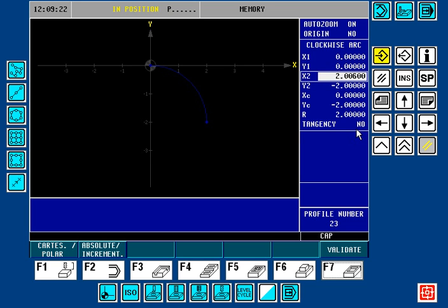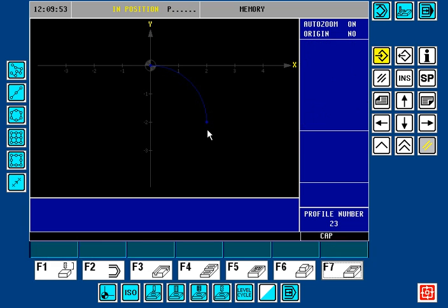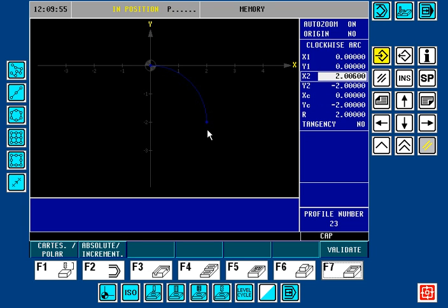Okay. If I remove the x center value as a fixed value and allow it to become a floating value, there, it turned purple. So this is one solution, is to allow one of the values to become a floating value. So the control will recalculate the x center to allow the arc to retangent between the 2 points by moving the x center over. But let's say the center, I'm fixed on that it must be 0. Okay, then I must become flexible on this endpoint.